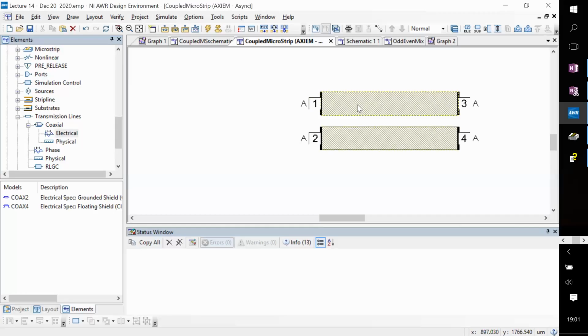Okay. This kind of a device, a directional coupler, is used for 2 different purposes. One is as a reference, like to create a tap of the signal which is flowing from 1 to 3, right? So there's some power going in from 1 to 3, and you want to actually know how much power is going, but you cannot put a power meter inside without disrupting the flow. You actually want the flow to be happening to wherever it's going, but you want to be able to get a sample of this. So you design a coupler which has a known coupling constant between 1 and 2,